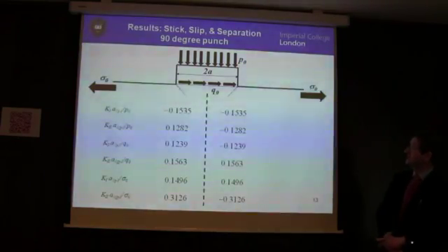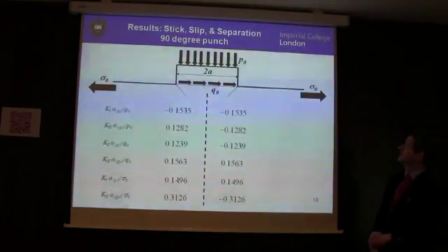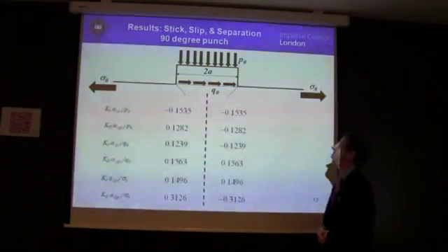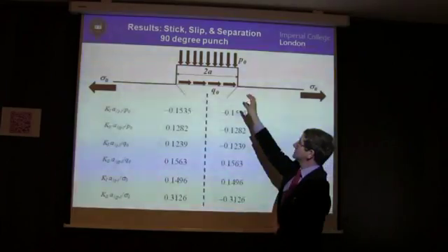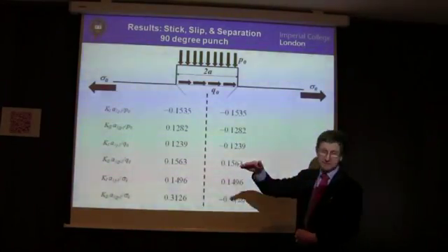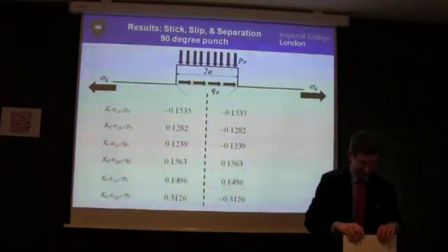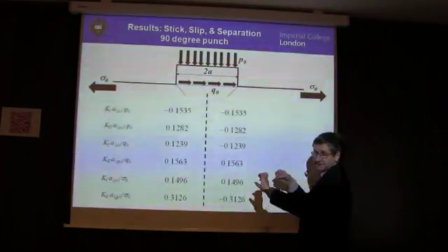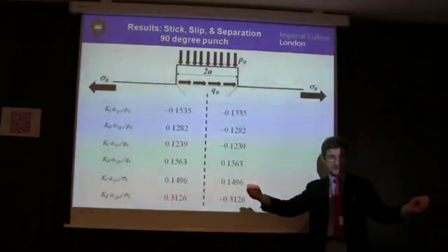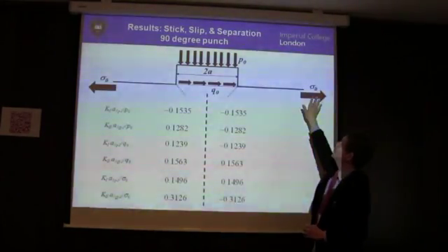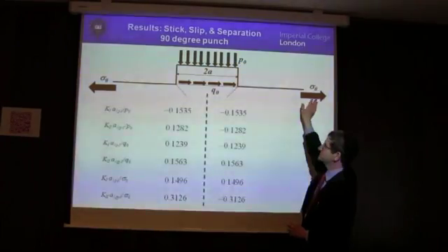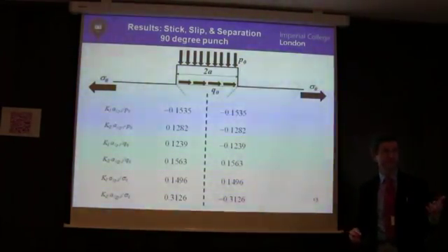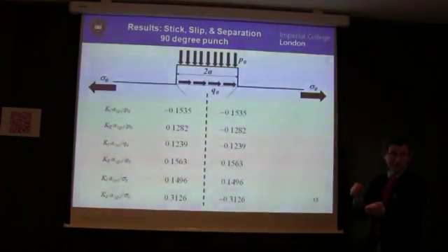So what I've just done here is I've just sketched out for this particular problem what the stress intensities turn out to be. So here's a block on a table again, where we're potentially pushing it down, we're shearing it, and we're also pulling the half plane that's underneath it. So all three of these modes of loading, the P0, the Q0 and the sigma 0, all excite both the mode 1 loading and the mode 2 loading.